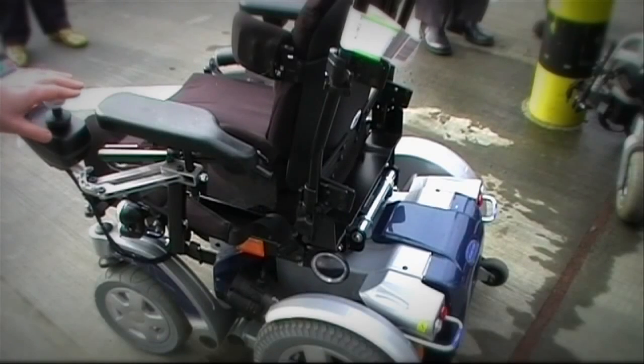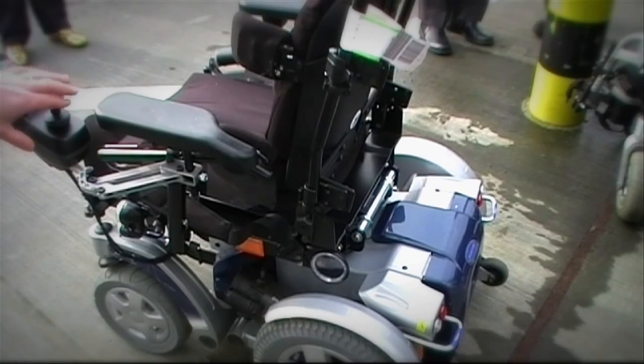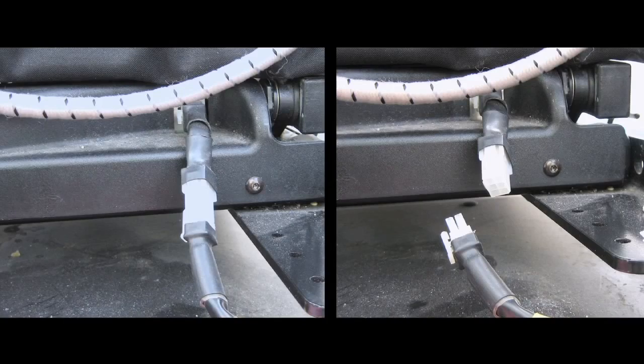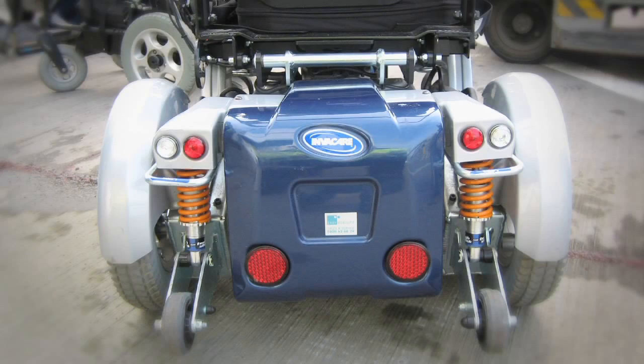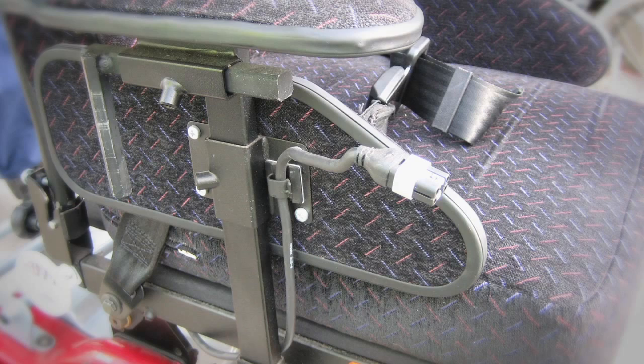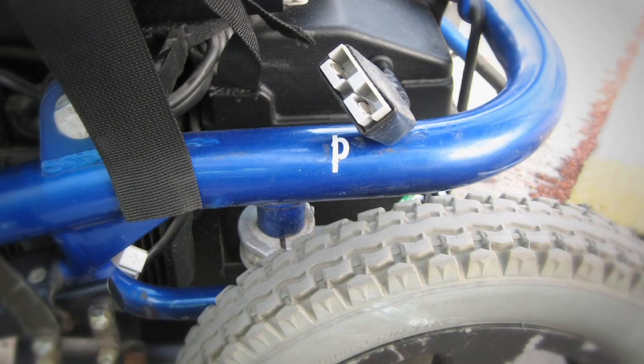Prior to loading, make sure that the device has been fully deactivated. Disconnecting or removing the battery is not required, since this can be very difficult to do and, if not done properly, can increase the risk of a fire. If that is the only option, in order to immobilize the device, make sure the battery is protected against short circuit by insulating the exposed terminals.